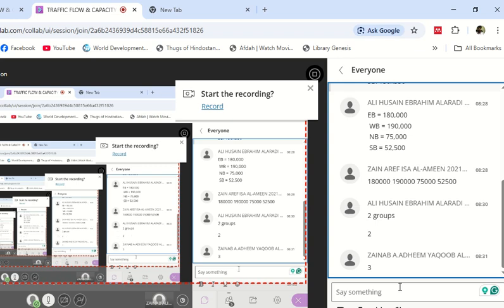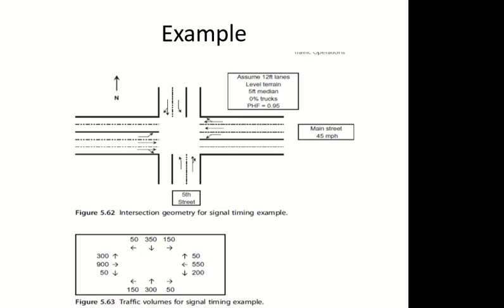Three, yeah. Okay, east-west would have three because you see all these lanes have something different in them. None of them is exactly the same. You can only put those lanes in one group which are exactly the same. So there is no exact similarity here. Yes, there is a common movement here, but then this one has a different one added as well. So we cannot put them together. So lane groups: we have 2 north-south, 3 east-west.